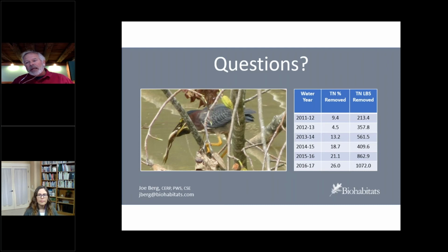But when it rained, the stormwater outfalls from the community would go into this area where our sand mound would backwater that and allow the water to seep through it. So that's in the Piedmont, and we've probably done 7 or 8 projects like that, small scale stormwater pond retrofits.